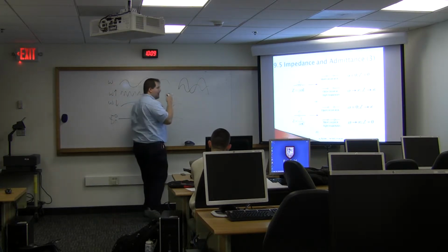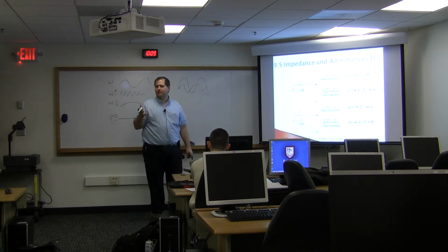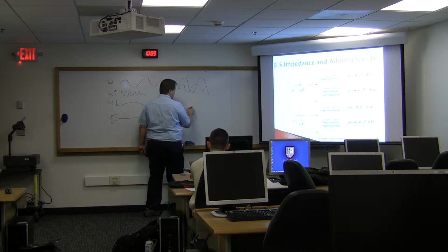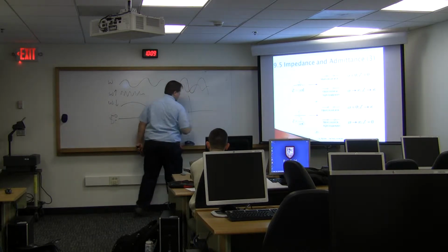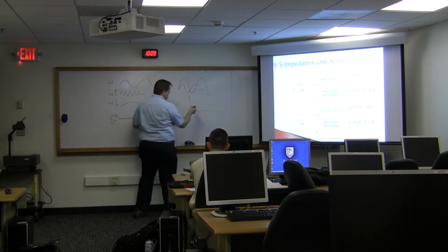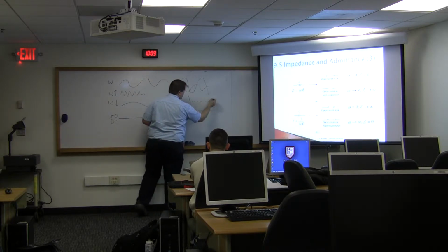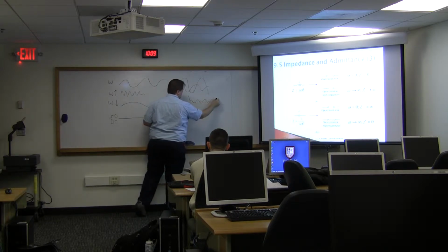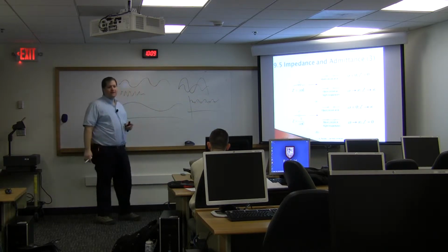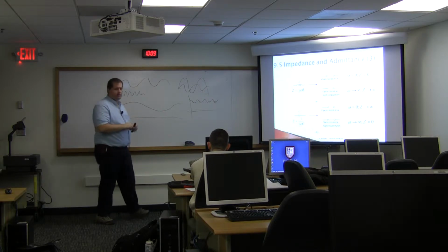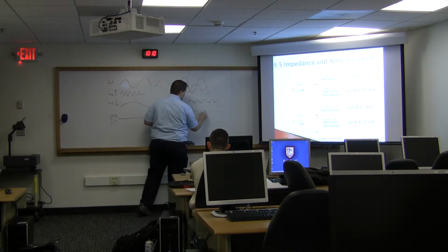Well, especially when you're doing the instrumentation amplifier lab, you might have had a DC bias that you put into your instrumentation amplifier, and then you had a little wiggle on it from the function generator. Right? And if you looked at that in the oscilloscope and you pushed the AC coupled button, it would have immediately looked like this.